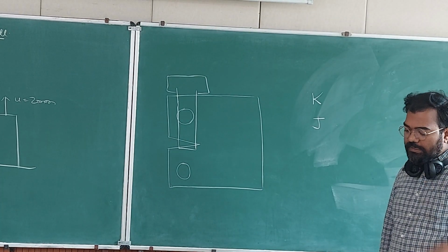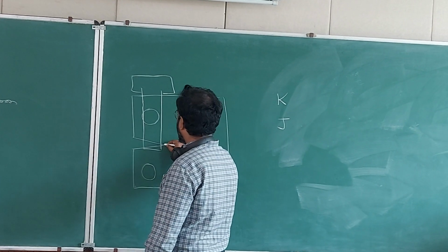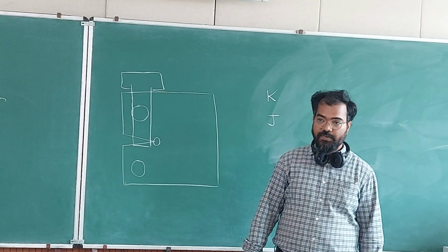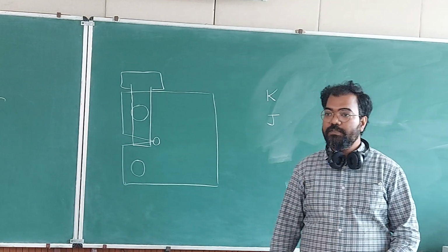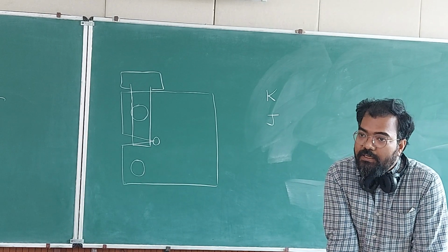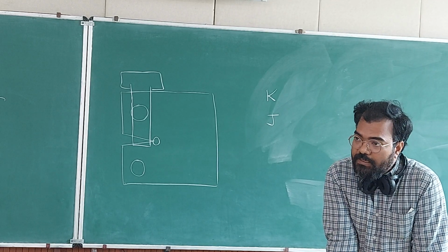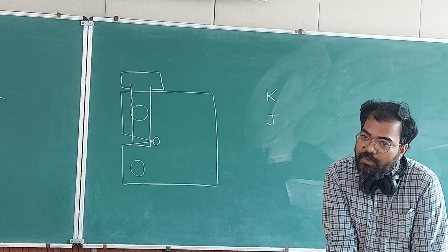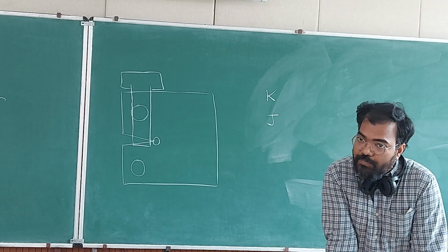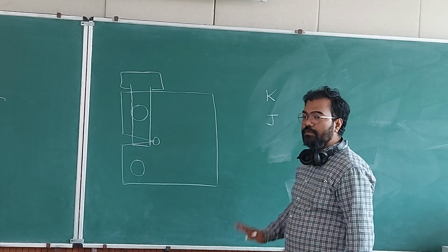As long as the deformation zone follows what we followed in plane strain fracture toughness testing, so that the theory of elasticity is valid in the majority of the volume of the specimen, then the stress intensity factor can be used to characterize the property of the material. So K is valid as long as the deformation zone is small.